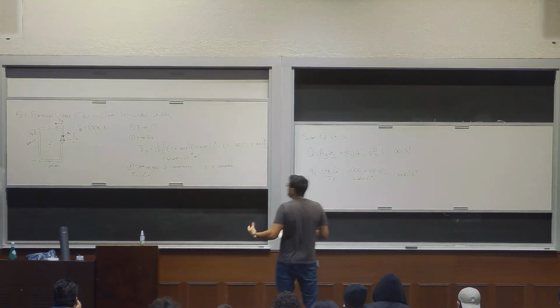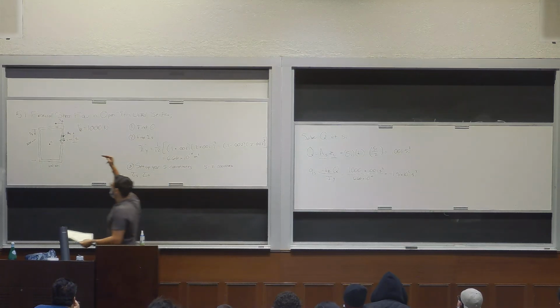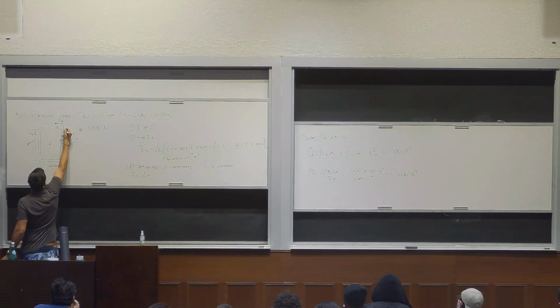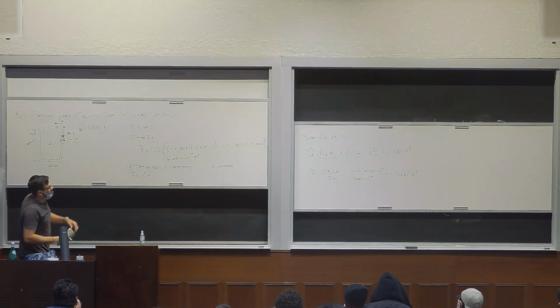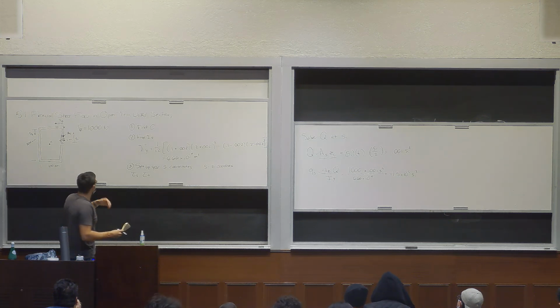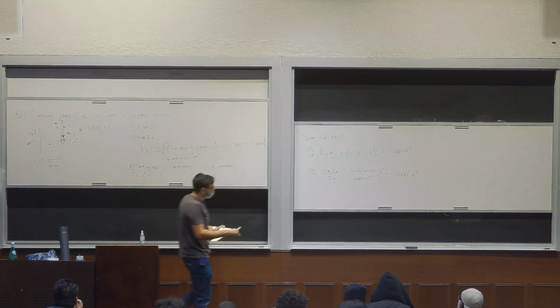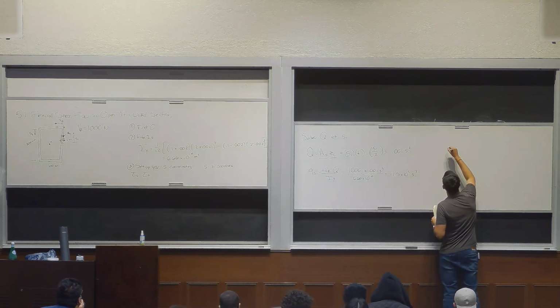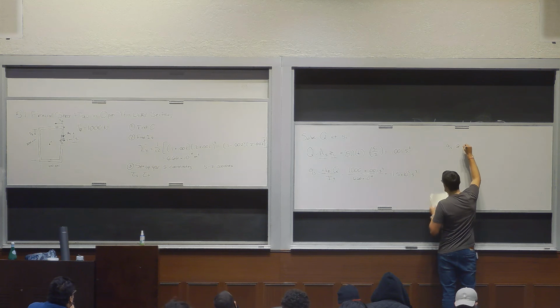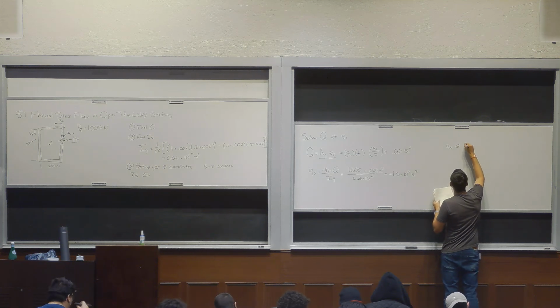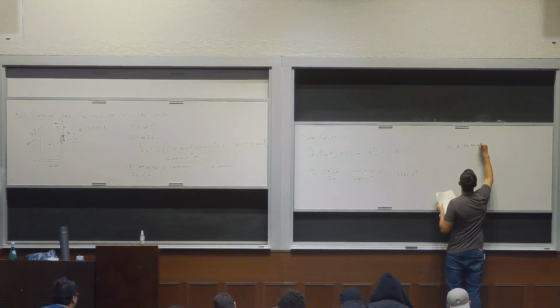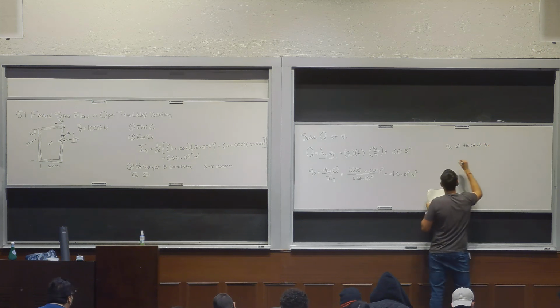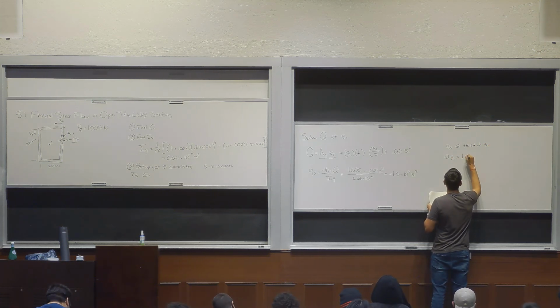The next step is to go to the end of that S1. We're going to take it to the maximum possible location. So here, we're trying to find q_s at the end of S1, and so at S1 equals 0.1 meters.